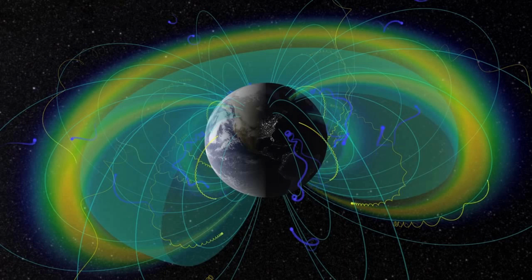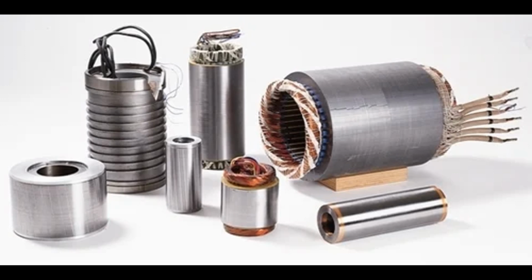In the context of alternators, induced voltage is a key factor in generating electrical power. Here's an explanation of induced voltage in the context of alternators. Changing magnetic field. When a magnetic field changes in strength or direction, it causes lines of magnetic flux to move. This change in the magnetic field induces a voltage in any nearby conductor, such as a wire. Faraday's law of electromagnetic induction states that the magnitude of the induced EMF, voltage, is directly proportional to the rate of change of magnetic flux through a circuit.